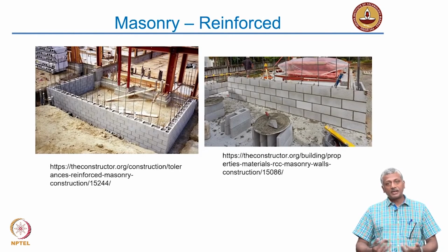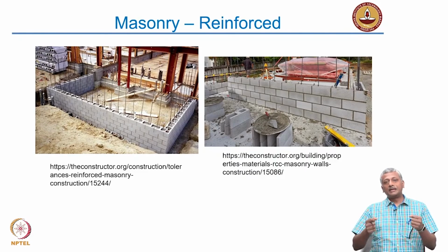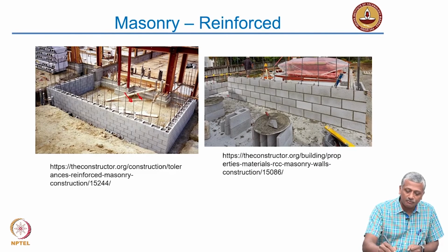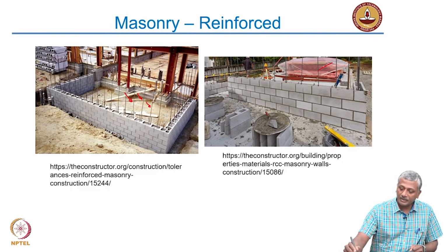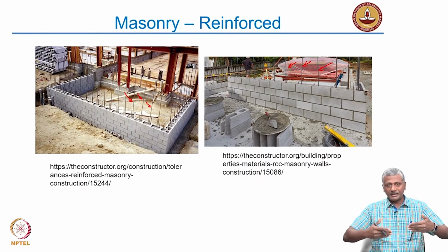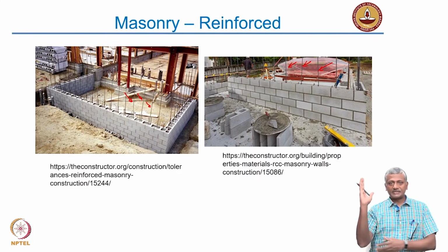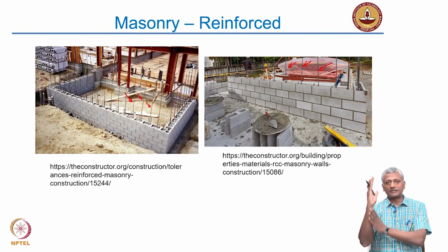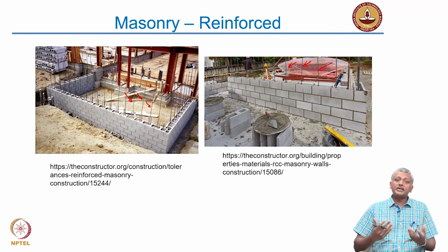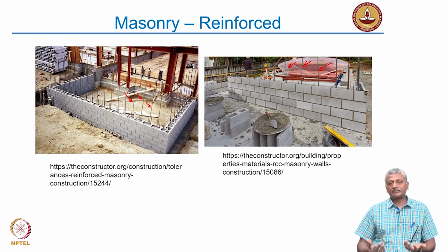Later, people realized you could produce masonry with concrete, and that led to the formation of hollow concrete units. The cavities inside concrete blocks were later reinforced with steel, so that now you could get a composite action out of the masonry wall, not just the compression load that it will take in plane, but also resistance to lateral forces because of the steel. So, we started utilizing materials and combinations of materials in such a way that they gave the maximum benefit.